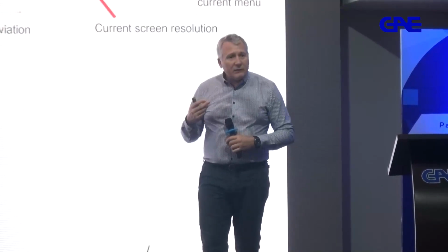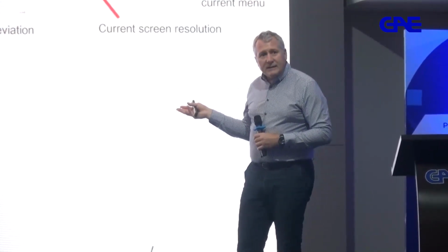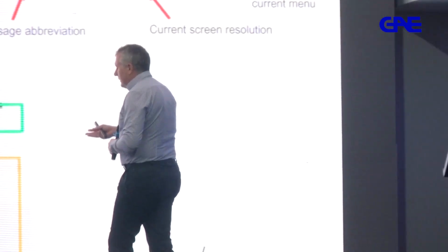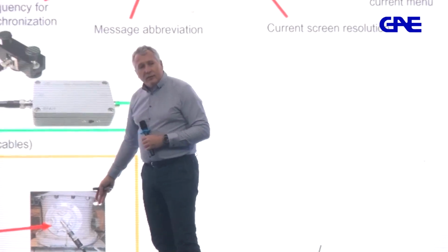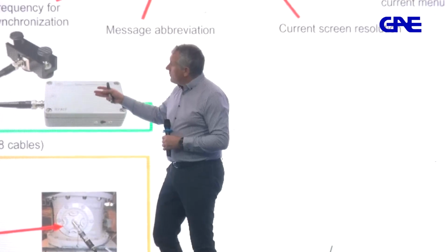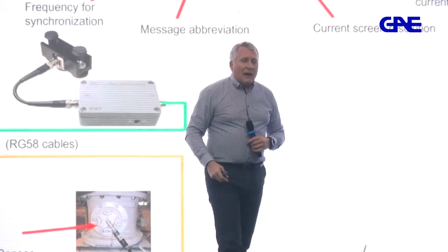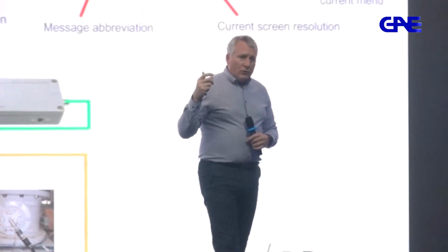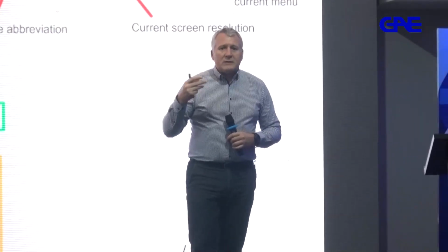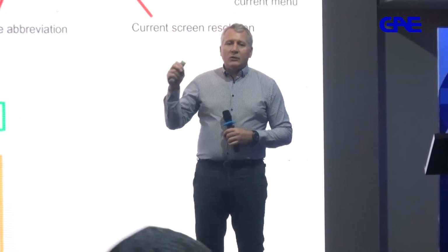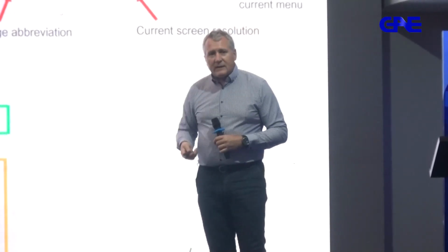The net result is that you can use such a multi-purpose device to acquire information either in a UHF sense from the GIS, or you can also use the device to acquire information acoustically. And you have to know the acoustic part is usually used to locate precisely where the fault happened. The UHF is more of a recurrent test procedure.